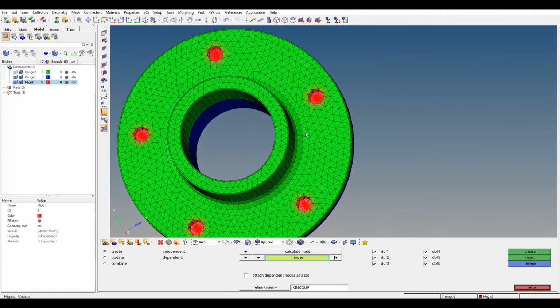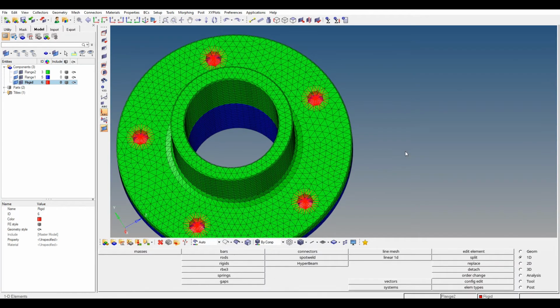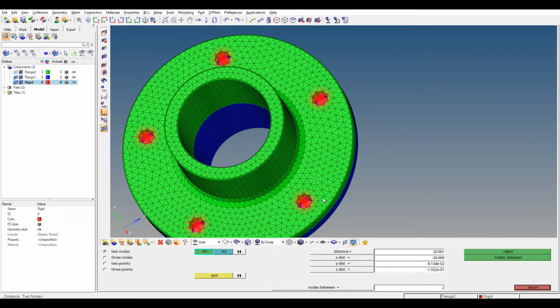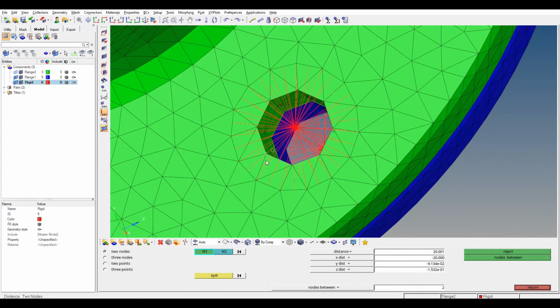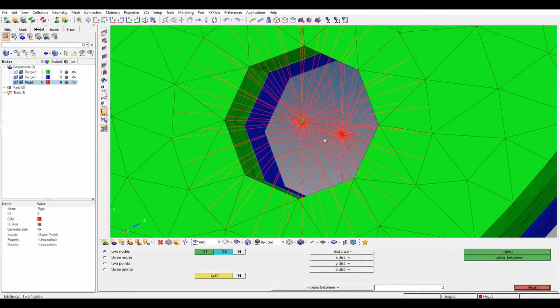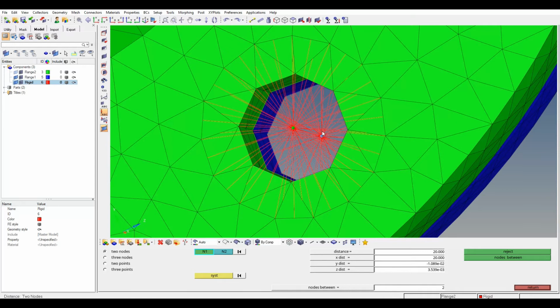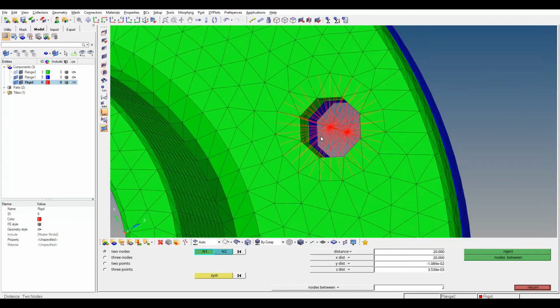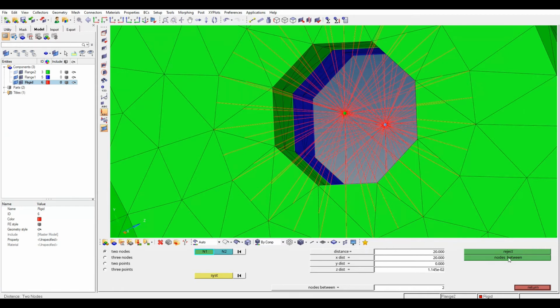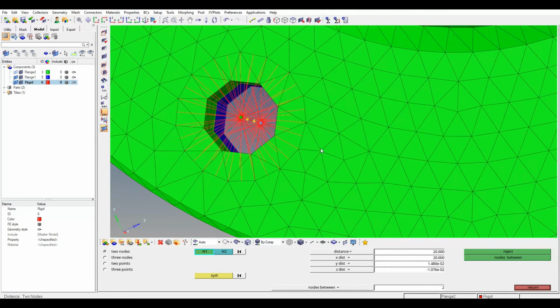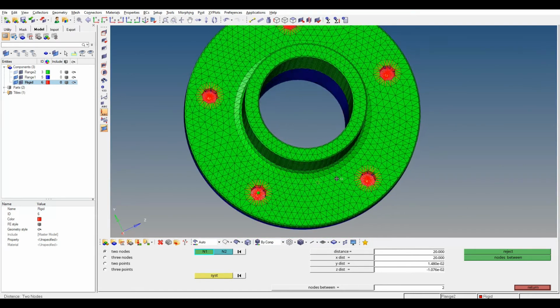What we need to do first is quickly press F4 and select nodes between the rigids. Okay, these rigids, this node and this node. Select nodes between here too, and click nodes between. Do the same for each rigid. I will pause it. Okay, so I've done it for all now.